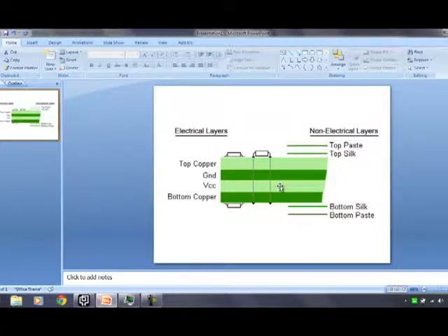What this also offered in terms of benefits was having a large area of copper, like for a ground plane, which can help with things like noise and EMC considerations within a design. Also, good grounding is always a good rule of thumb for all electronic circuits, especially digital ones. So this was maybe a couple of the benefits, especially in high-speed designs. This kind of usage of planes can be useful too.